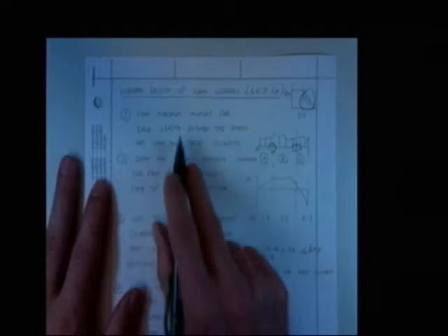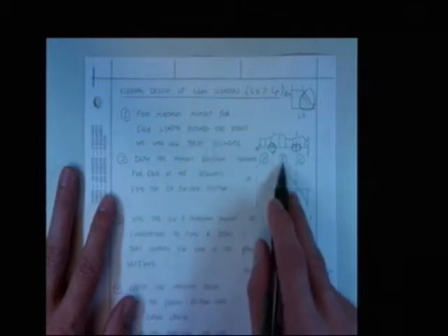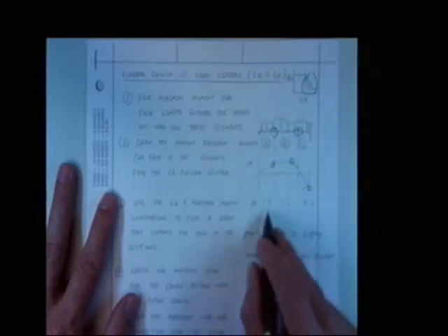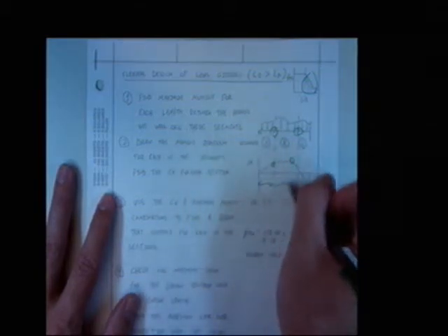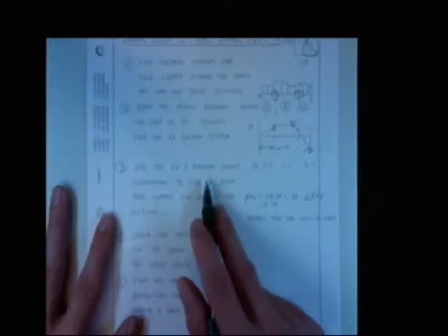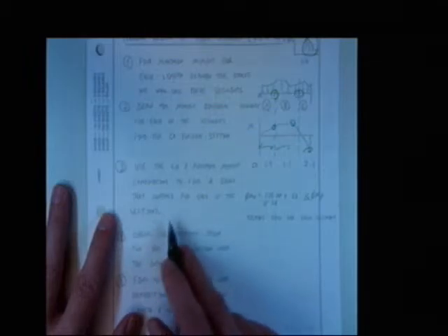So you're going to find the maximum moment for each length between the braces. We'll call these segments. Find the maximum moment for A, B, and C. You're going to draw the moment diagram for each of the segments and find the C sub B for each section. So you have maximum moment, C sub B for each section, and L sub B. You know what this is for each section, right? Use C sub B and the maximum moment combinations to find a beam section that controls for each of the L sub B's.